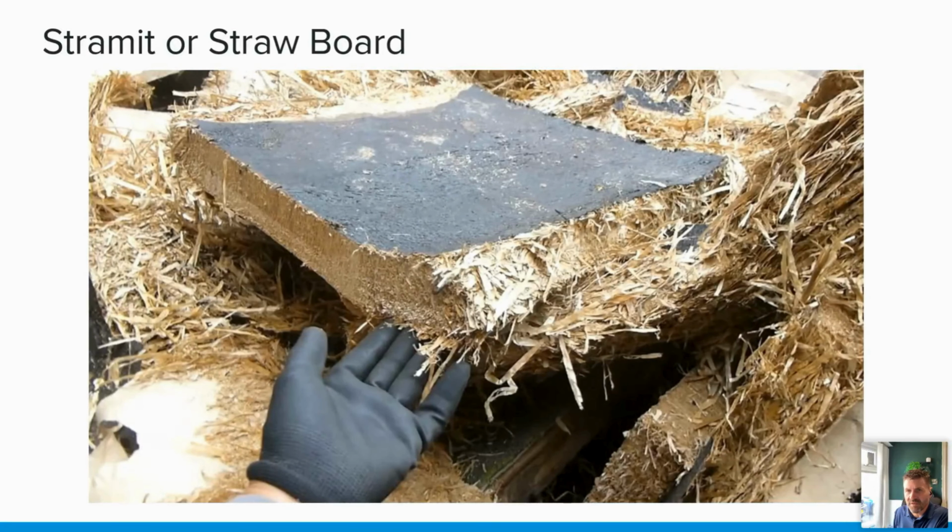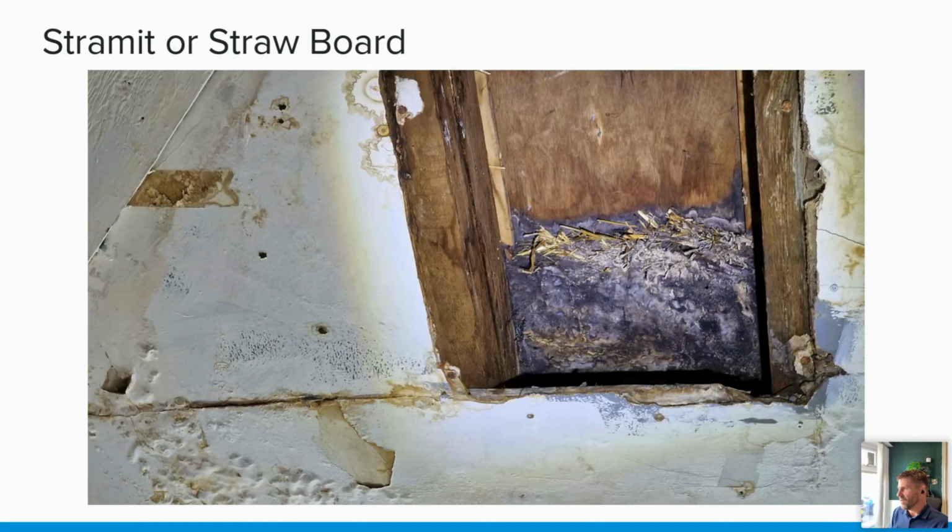How to recognise that? From the bottom, you can sometimes see, from the underside, it just looks like hay or straw. It is literally straw. And from the top, it's more yellow in colour if it's dry, more yellow than a concrete deck, and you can see the straw there.